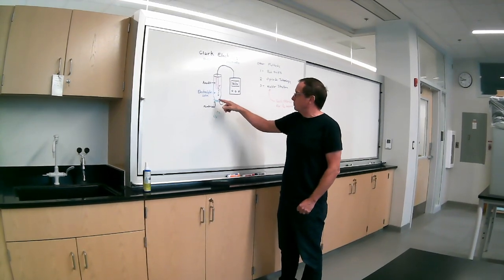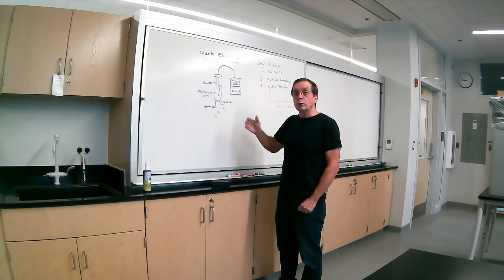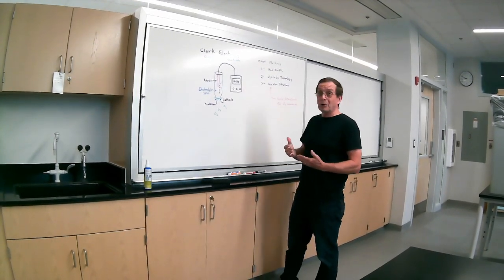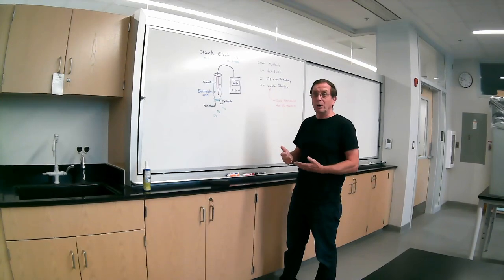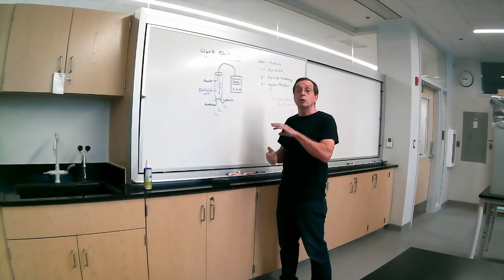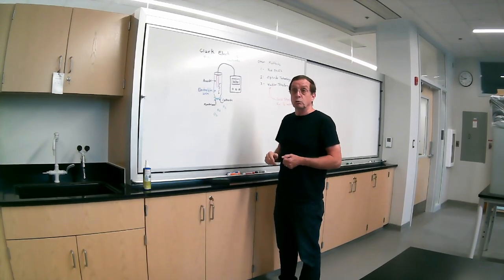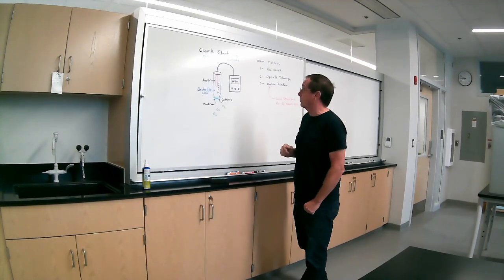So we move the tip of the probe around and around so that we renew that boundary layer against the membrane continuously, because if you don't, and you just walk away from it, you'll come back and you'll see that the boundary layer is completely depopulated in oxygen, and your reading is measuring 0. Okay, so that's not what we want to do.